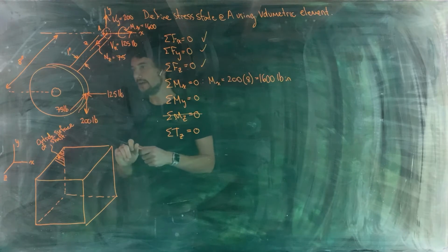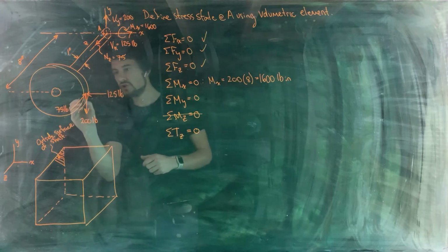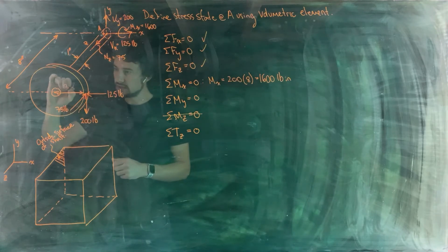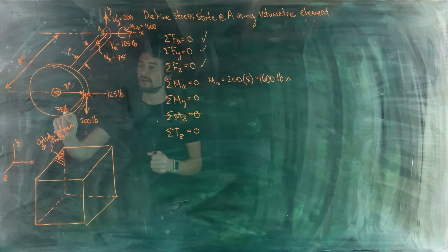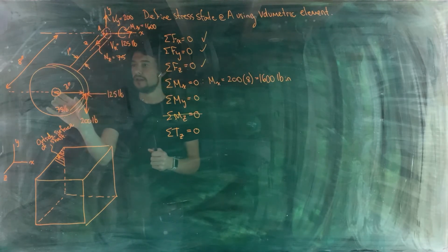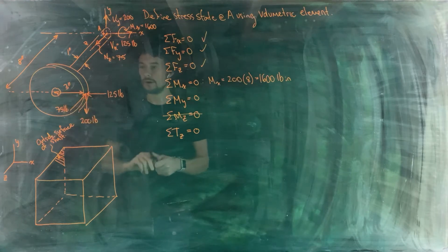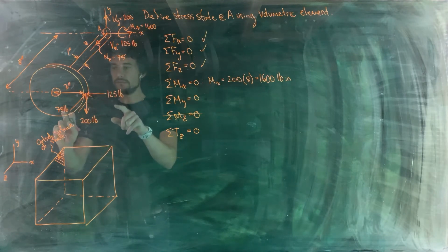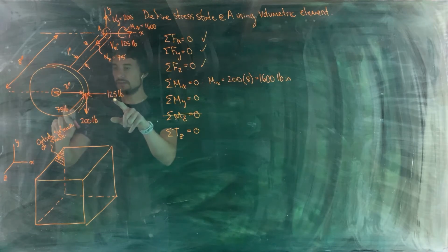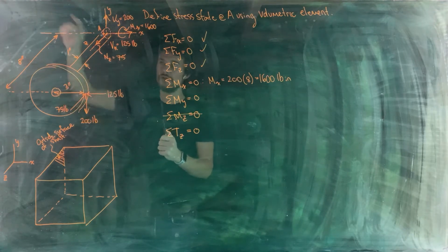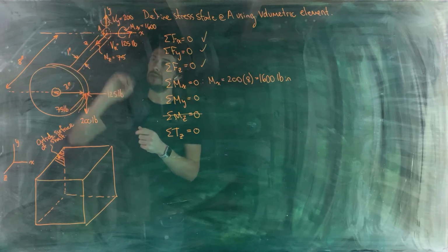And here I can see I forgot another dimension on the drawing that I should have put on. So this distance from the edge of that gear to the center location is 3 inches. Okay, so the 75-pound load doesn't cross the y-axis in three-dimensional space. If you take the line of action and the y-axis, they're always a minimum of 3 inches apart. Now, that's going to create a moment about the y-axis in the opposite direction. So looking at the relative magnitudes of the moments created by 75 pounds and 125 pounds, 125 multiplied by 8 is going to be a lot bigger than 75 multiplied by 3. So the net moment is going to be in the direction of the 125-pound load. So we're going to need an internal moment in the opposite direction.